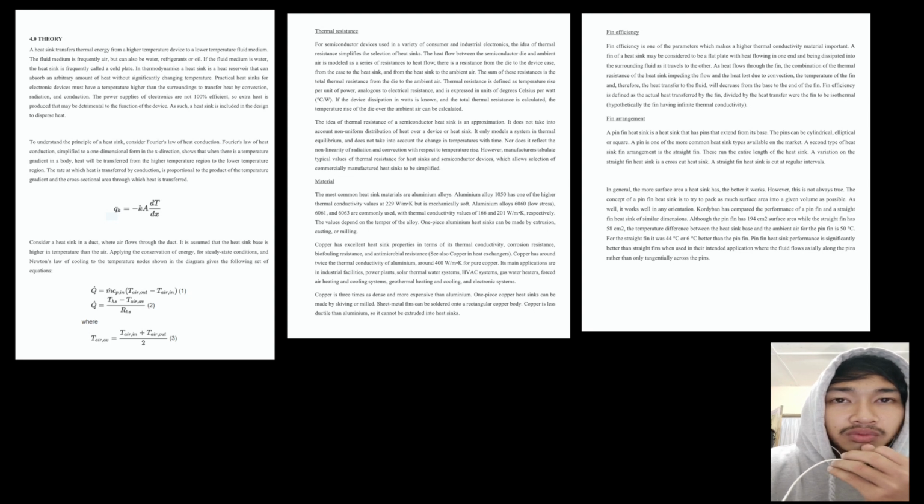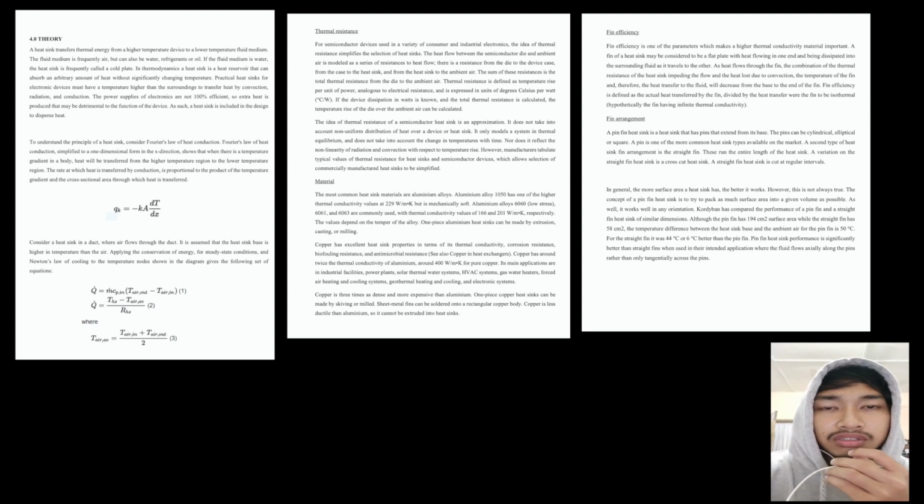The rate at which heat is transferred by conduction is proportional to the product of the temperature gradient and the cross-sectional area through which heat is transferred. So the formula for Fourier's law is Q equals negative K A dT per dx.